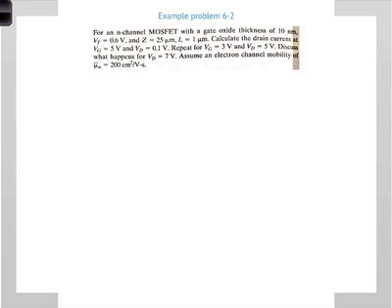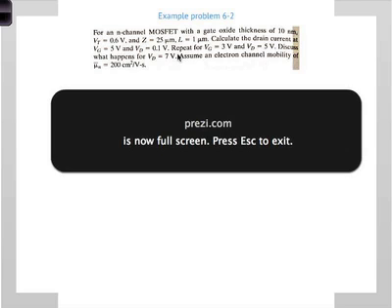So what's VG minus VT? It's 5 volts minus 0.6, so it's about 4.4. And VD is 0.1, so it is not saturated. It's a linear regime. The rest is pretty straightforward, you just plug in the numbers. Not so important. Now what happens when VG is 3 volts?